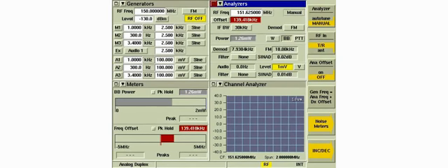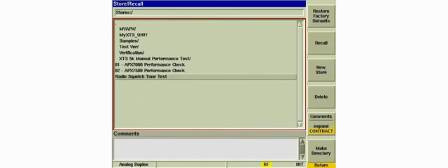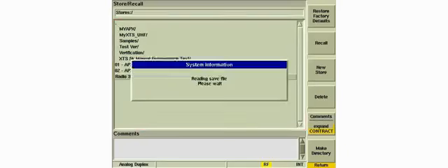It's obvious there are numerous limit values to set. In fact, setting up the limits each time a new radio is tested would take more time than the actual test. However, if the limits are stored as a setup, recalling the setup takes very little time. In this example, the settings to test a particular radio model's squelch tone parameters are stored as a setup. After the setting is recalled, the radio only needs to be keyed to perform the test.